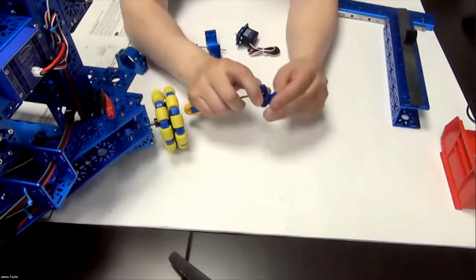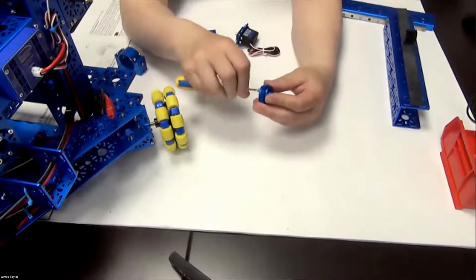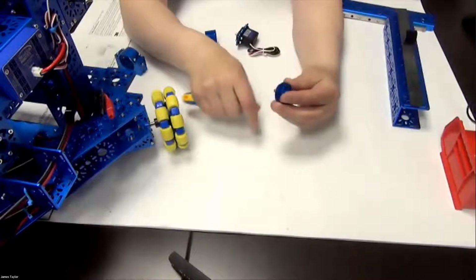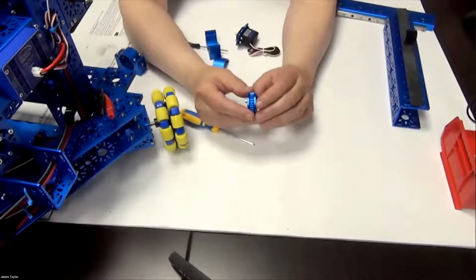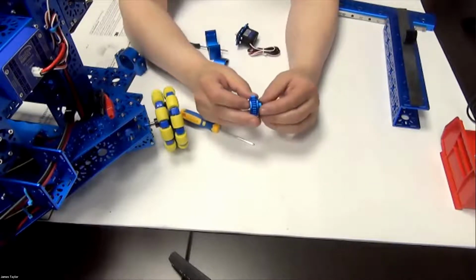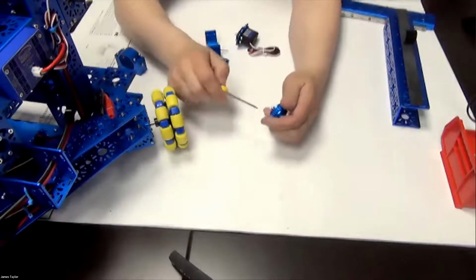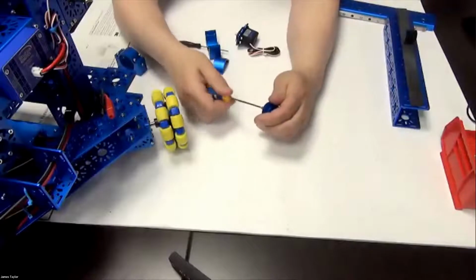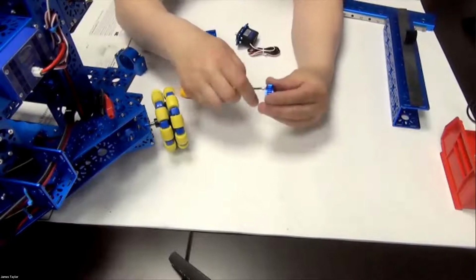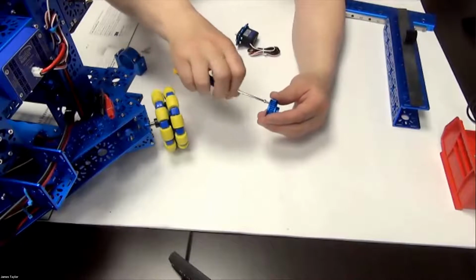And as it comes out the other side, we are going to thread that into another shaft hub. It's a little bit tricky because remember you're going from one thread through another, so you can get some offset in there. What that does is provide me double the strength, which is what I want to do. It's up to you if you put one through one way or the other. If you want to have 4 set screws on and you have enough clearance in your design, you could mount both shaft hubs on either side.